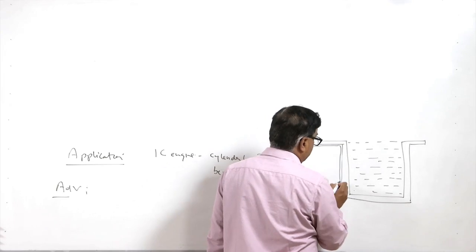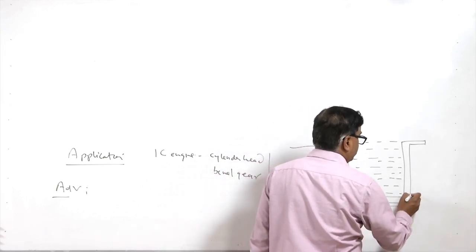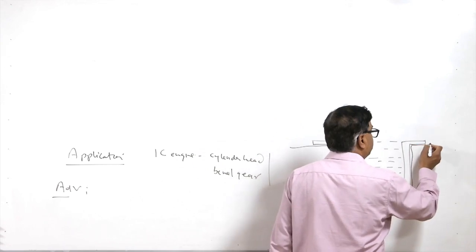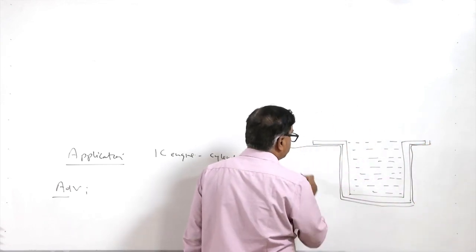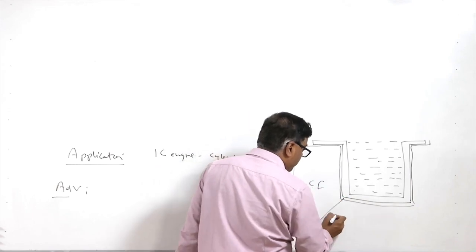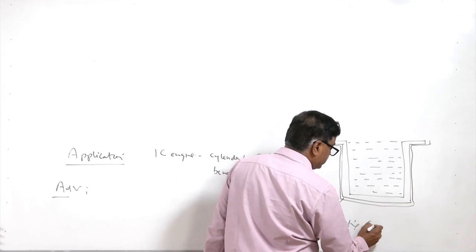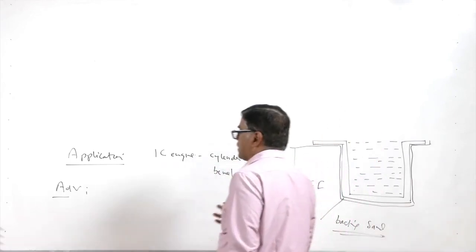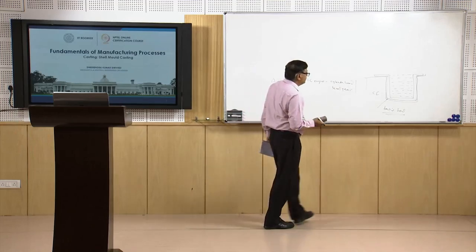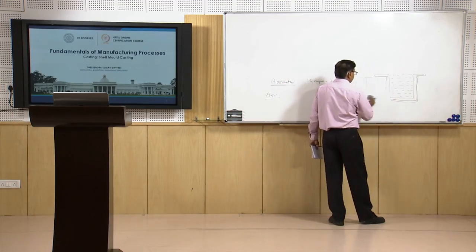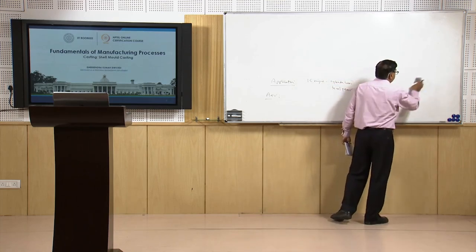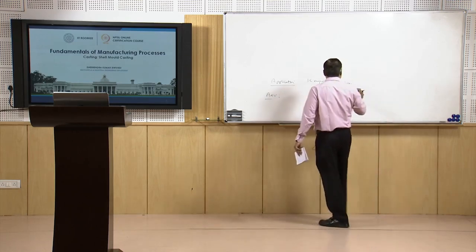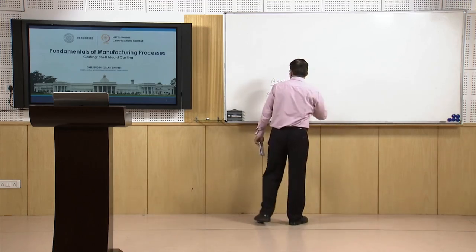It may be a grey cast iron support of the same shape as that of the mold, or we may provide a backing of sand from all the sides, so that it can take the metallostatic pressure and the load of the molten metal without fracturing of the shell, so that after solidification a suitable casting can be achieved.